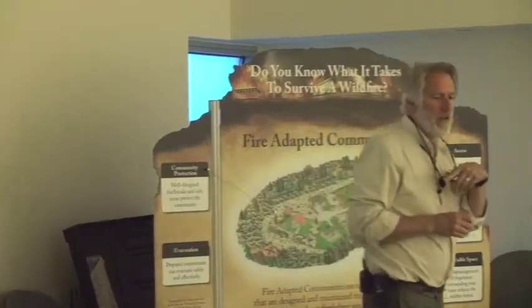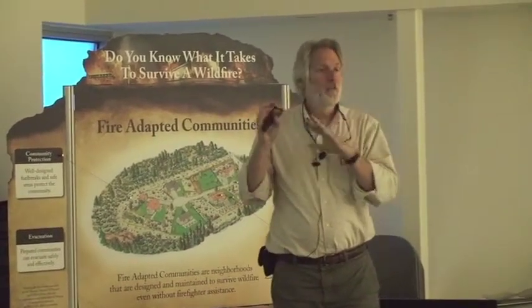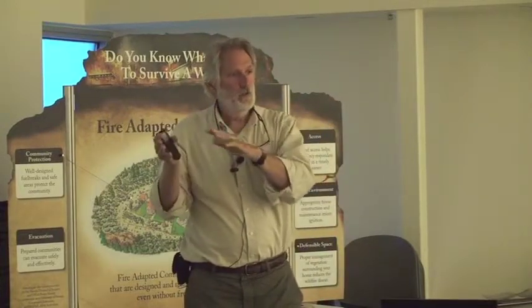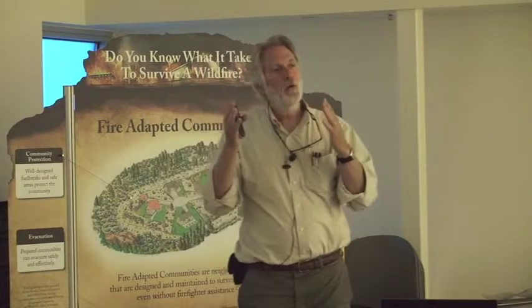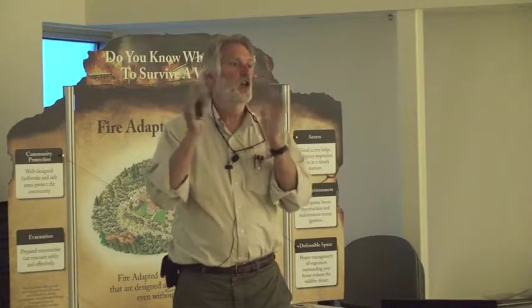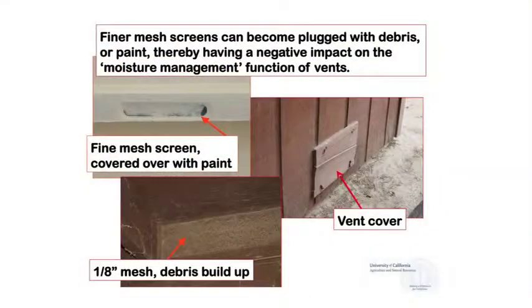Some testing that we've done and some testing that's been done at other labs have shown that depending on the combustibility of the fine fuel, how fine the fuel is, you can have fairly small embers igniting that fuel. And then the flame from that small fuel fire will then provide a flame contact exposure to the larger structural members in the attic, and you end up having an attic fire. So one thing is for sure, finer mesh screen is better, but finer mesh screen is easy to plug up.